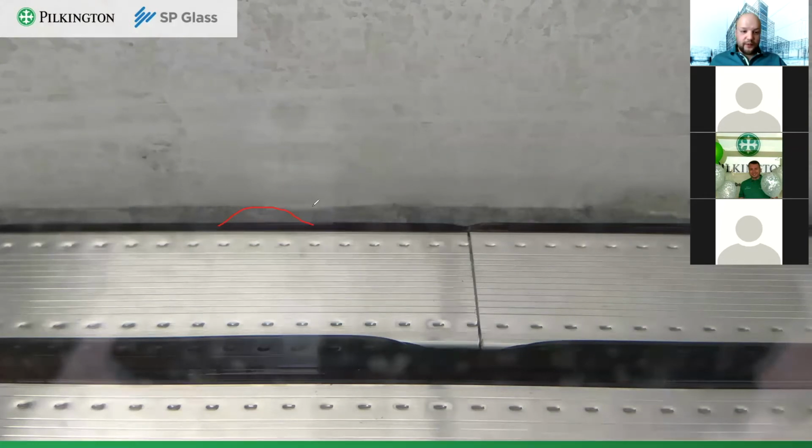First of all, if you put too much butyl on both sides of your spacer, then it can get heated up by the sun, for example, and begin to expand slowly. Now, while not a really critical fault, this is a visible fault, visible to everyone, and to the customer also.